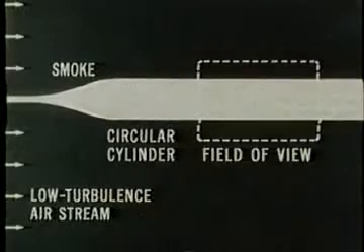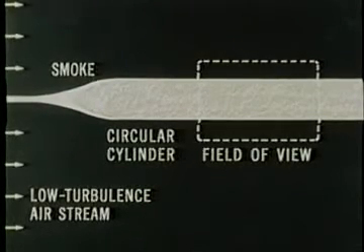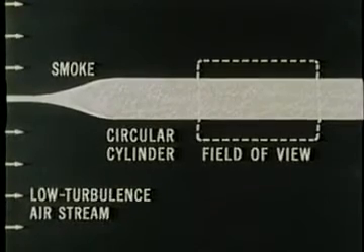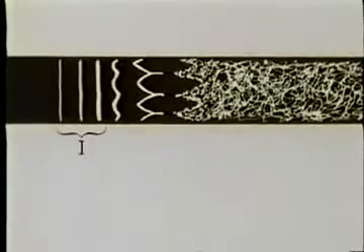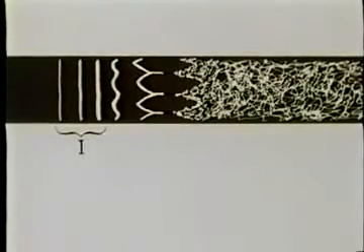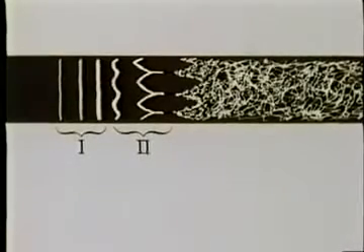A slight adverse pressure gradient causes transition to occur within the field of view. The steps in the transition are very complicated and interdependent. Of nearly two-dimensional waves, the Tollmien-Schlichting waves, followed by the appearance and growth of three-dimensional disturbances associated with streamwise vorticity. Then turbulent spots can be seen. And finally, fully turbulent flow appears. Here, the exact position where growth of two-dimensional disturbances begins depends on random small-scale fluctuations in the flow, and therefore varies with time in a random way.